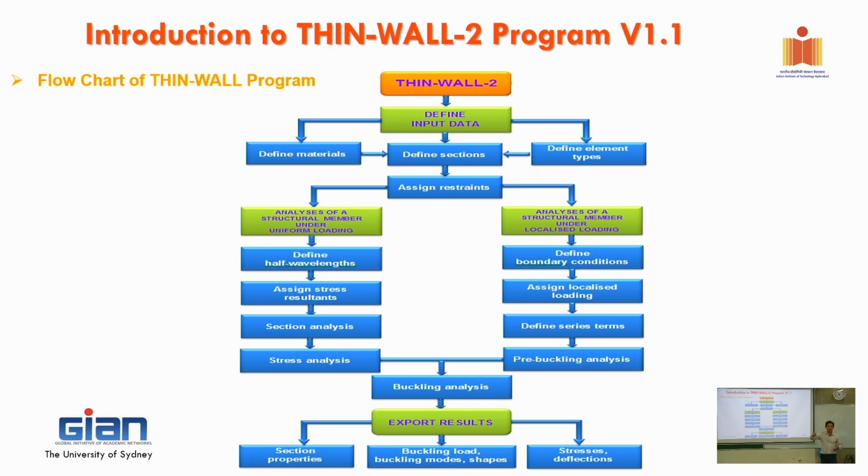As I explained to you, it is like a beam sitting on a support under a highly concentrated load. It might cause a web crippling problem, or localized loading on your member. The load acts at a very small area and causes the web crippling. Then it is called localized loading, and you follow that to design. Okay, so those are the two functions that you do.